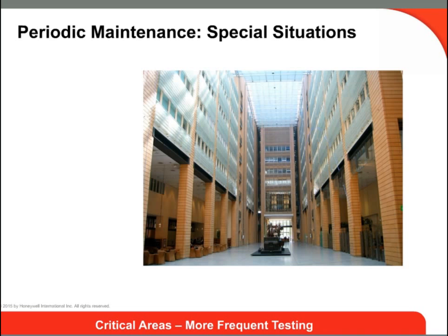Additionally, whenever a building is remodeled or renovated, this is an opportunity for debris to enter the system. It is a good idea to perform a damper inspection after work is complete to ensure the system is ready for an emergency.